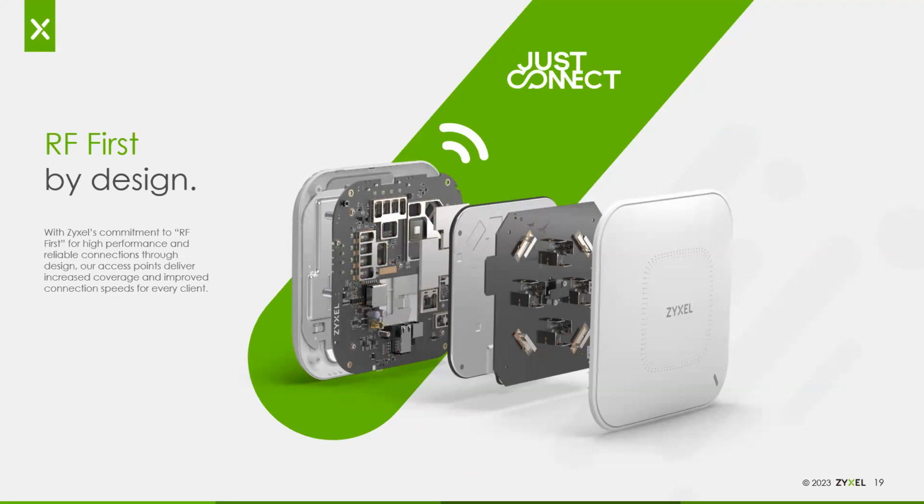The reason for that is this RF first design, and it's not just to help reduce EMI on the board itself. We also build in 4G and 5G shielding to prevent 4G and 5G signals from interfering with your Wi-Fi. A lot of your cellular signals out there border the 2.4 or the 5 gigahertz space used by Wi-Fi, and you can have edge bleed over, which causes interference. This is especially true of your larger buildings where cellular signal doesn't penetrate, so they're using some form of DAS device to distribute the signal inside the building. So you can have a DAS broadcast just a few feet down the hallway from where your access points may be, and that can cause interference. Our shielding helps prevent that.